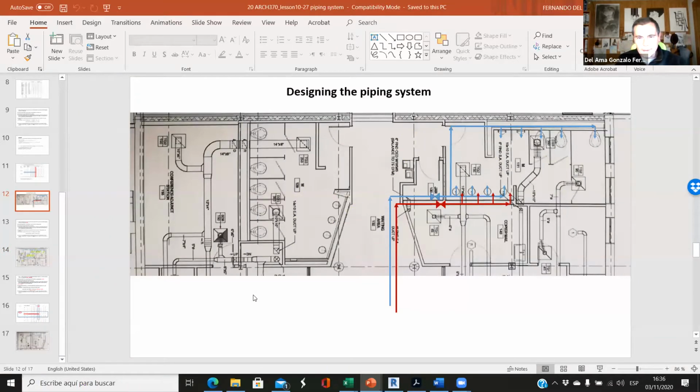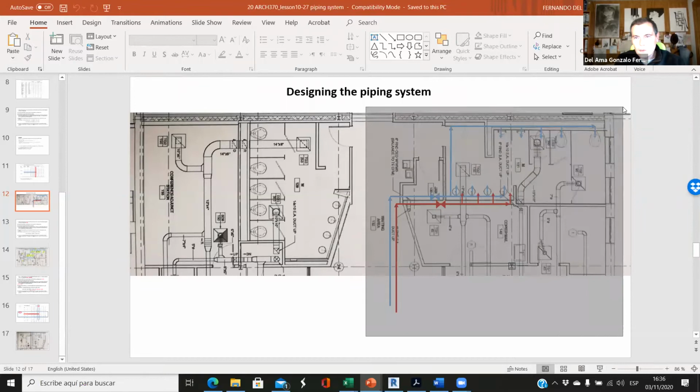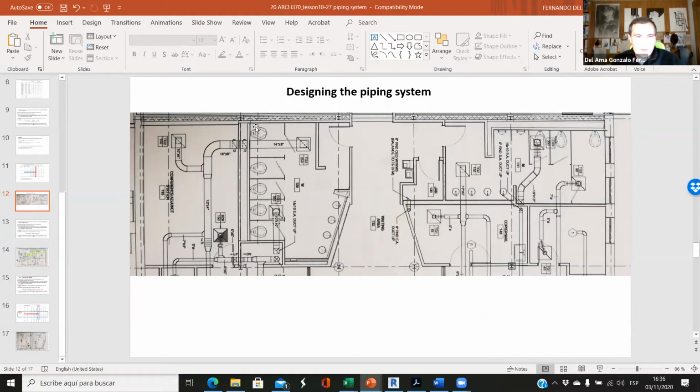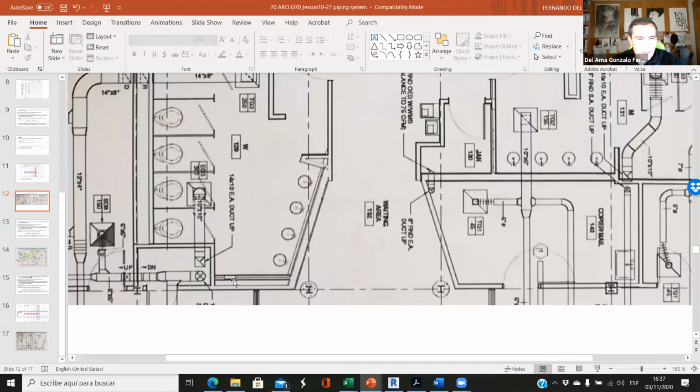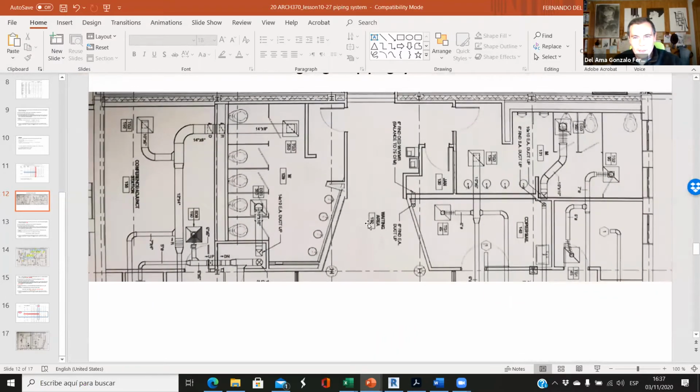So if you remember, this is the TDS center. I told you that we always have this double wall with an air cavity here where the toilets are. Okay, so we will use this element, or we will use this space to place our stacks, the rain stack, the gray water, we will use this. Or for the sinks here you see that we have another double wall. Here we have another shaft. Okay, so when we have a shaft here, we can have air ducts, and sometimes we can have stacks and water pipes. Okay, but at the end, we are using a lot of space.